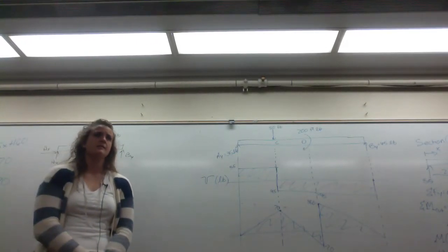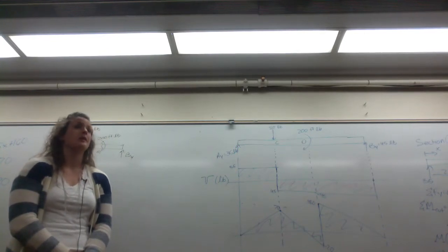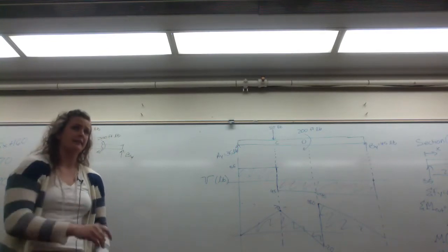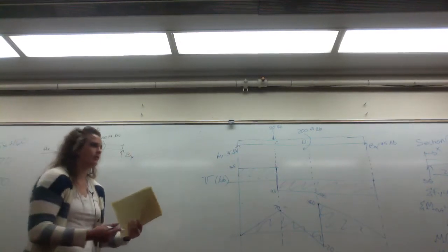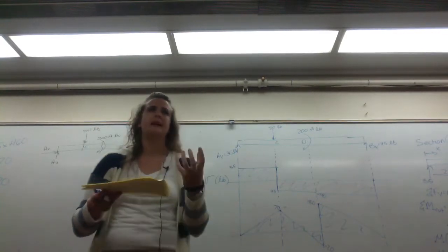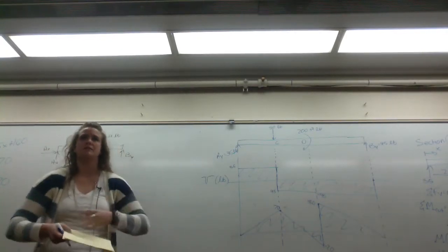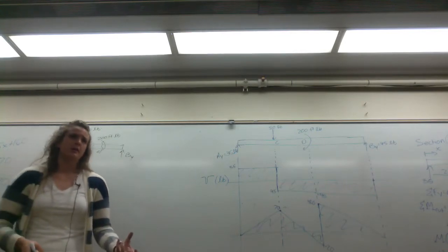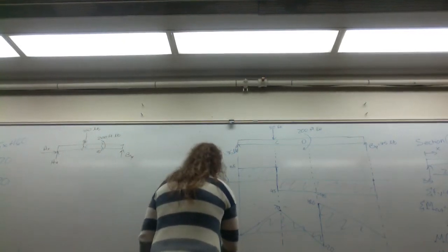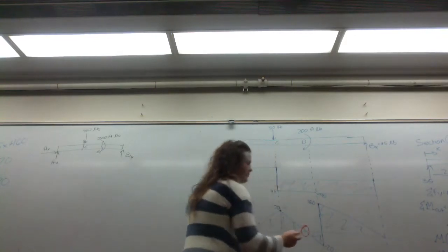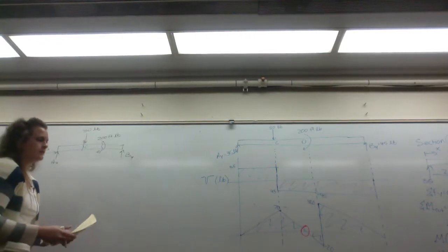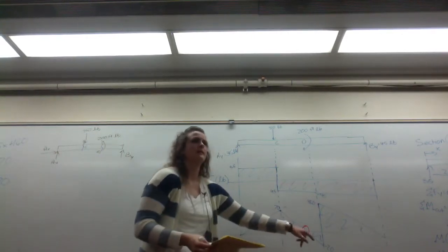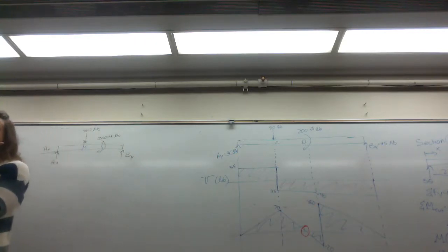Yeah, Curtis? Where what is closest to 0? Exactly. You would do it where your moment is 0. Because if you make a cut, you're going to have to connect it with some sort of gusset or pin connection, right? It's not going to be a continuous beam. There's going to be different materials. Things are going to change. But at the point where there's 0 bending moment is an excellent place to cut the beam so your connections don't have a large amount of torque applied to them.